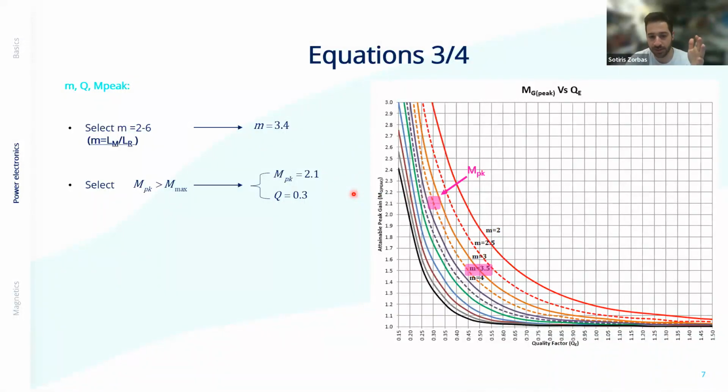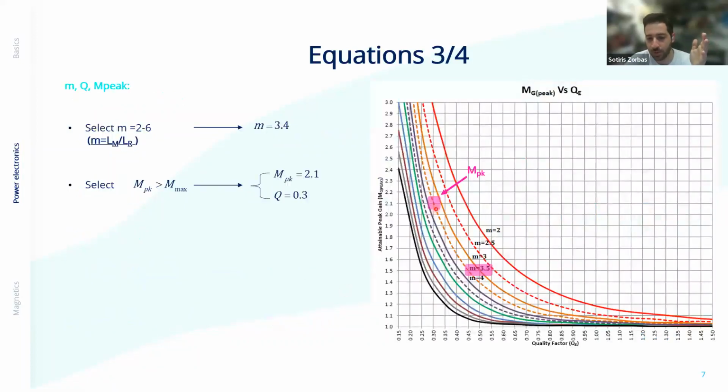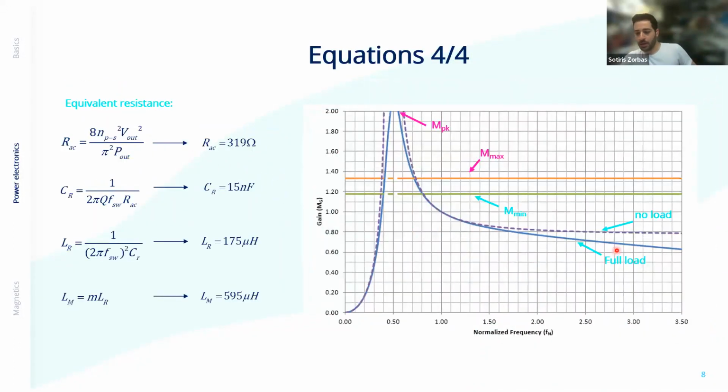In simple words, we have here 1.33. Usually a good thing to do, always to do, is to give it a little bit of wiggle room. So add 30% more than that, which would take you to around 1.5. If I select anything above 1.5, then I'm pretty much covered, as you're going to see in the next slide.